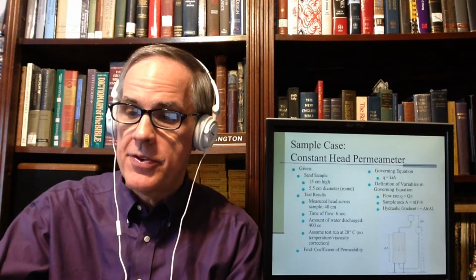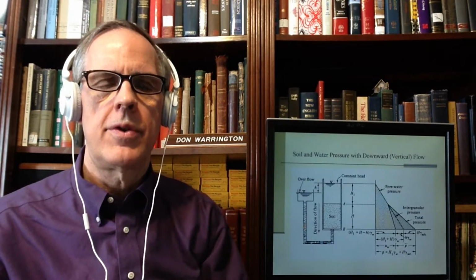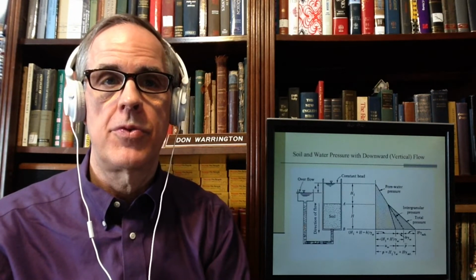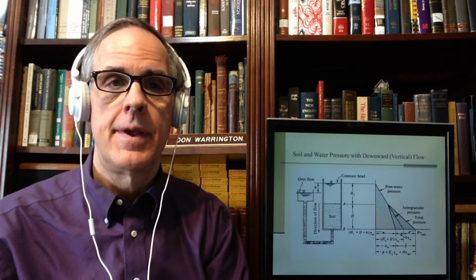If I do a lot of this stuff and I do some math, I rearrange and I can get K20 out of that using this equation without having to do a lot of pre-conversions. And all I do once I get there is I plug and I chug, and you can and should check this to make sure I'm not just blowing smoke in your face. So that is the constant head permeability test.